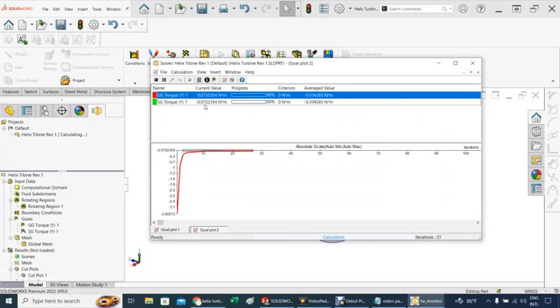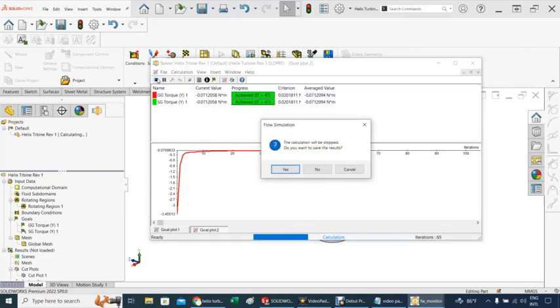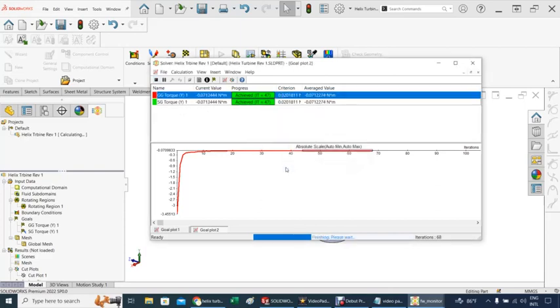The value before was settling at about 0.8 negative, and this is settling to 0.7 negative. And we can cut this short. I mean, we know that it doesn't change much. As you hit in the progress bar here, it already converged within 47 iterations. That's more than enough, so we can bail out from here just to do this fast. So we want to stop it, and let's say yes, so that I can save the result, and we are convinced that this is good enough.